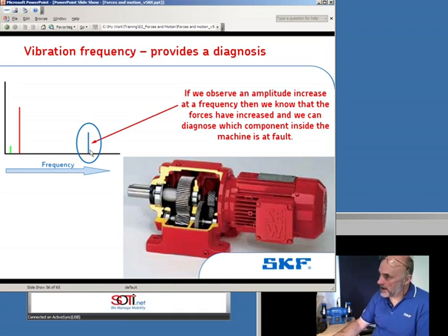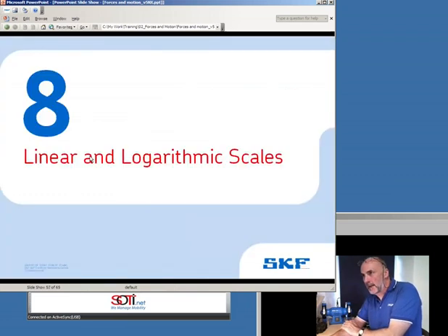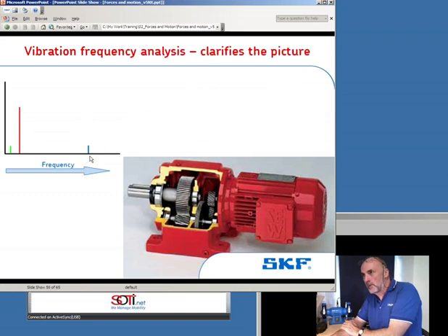And if it's really small in relation to the unbalance, for example, it will not show up on your RMS reading. You have to do frequency analysis, again, if you're interested in gearboxes, because this peak could be quietly growing on you and you won't see it growing.